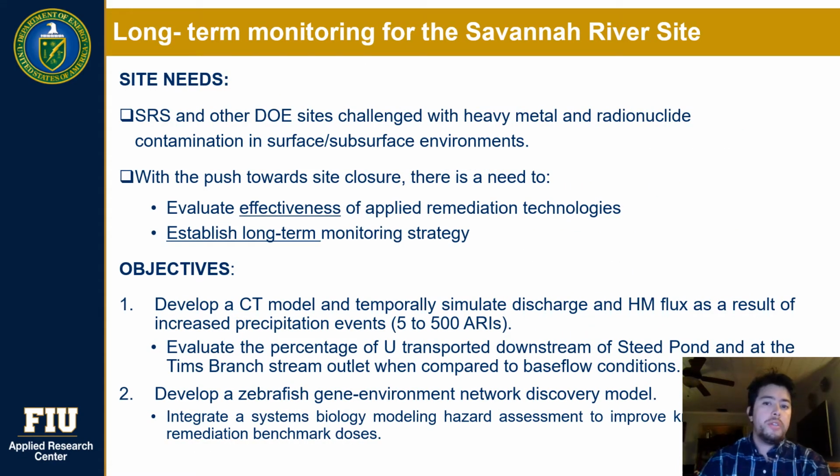So what does long-term monitoring for the Savannah site mean? Not just SRS, but other DOE sites are challenged with heavy metals and radionuclide contamination, both in the subsurface and surface environments. Many of these sites are pushing towards site closure. So given that they want to give it back to the community and to move forward with site closure, they would like to evaluate the effectiveness of the applied remediation technologies. Most importantly, they're interested in establishing a long-term monitoring strategy.